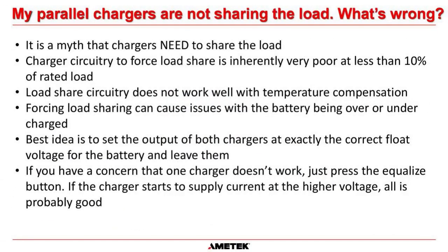Also, it has to be noted that the charger circuitry to force a load share is inherently very poor at less than 10% of rated load. That goes for nearly all manufacturers. And in most circumstances, you'll find that most chargers are very lightly loaded. It will be below that 10%. So the forced load share is not going to work very well.